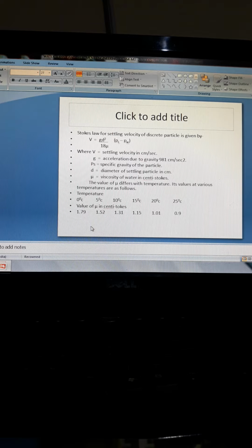Hence a large proportion of the suspended particles is removed by settling down to the floor, and at the end of this designated detention period, the outlet valve is opened so that we can withdraw the settled water, which is comparatively clearer because a major portion of the particles have been removed from the raw or incoming water.